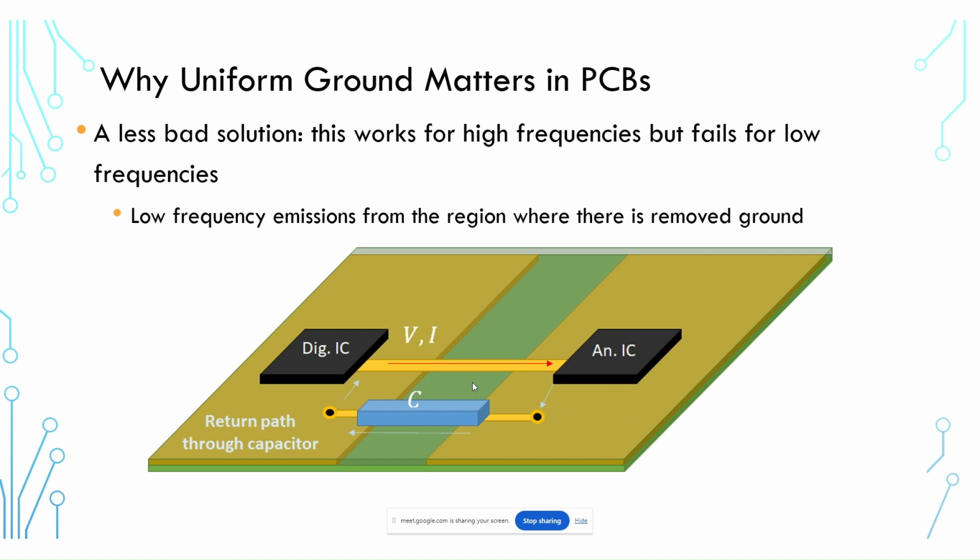So this is one of the most commonly suggested solutions here to allow someone to split ground planes and then try to eliminate the EMI problem that they just created by splitting the ground planes. But then it creates all this extra work, and so I think there's really no point in doing this.